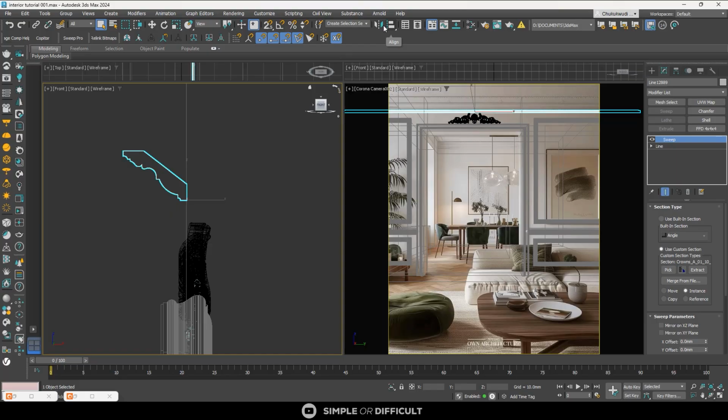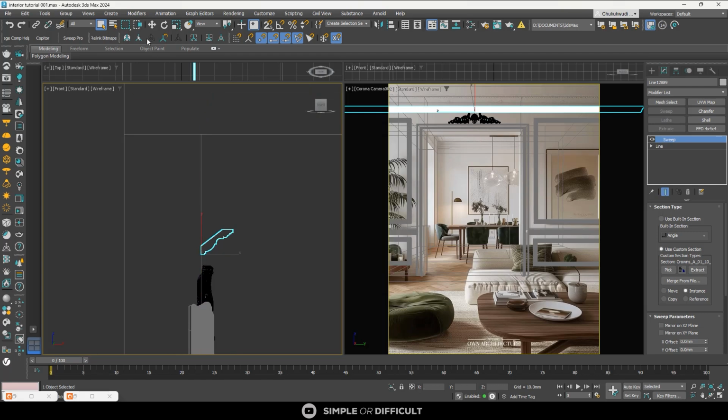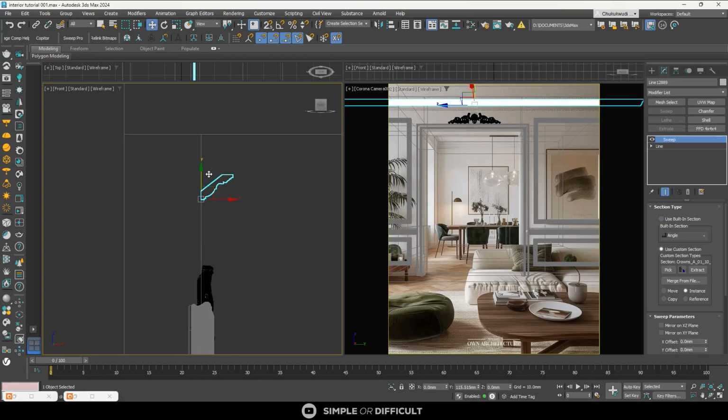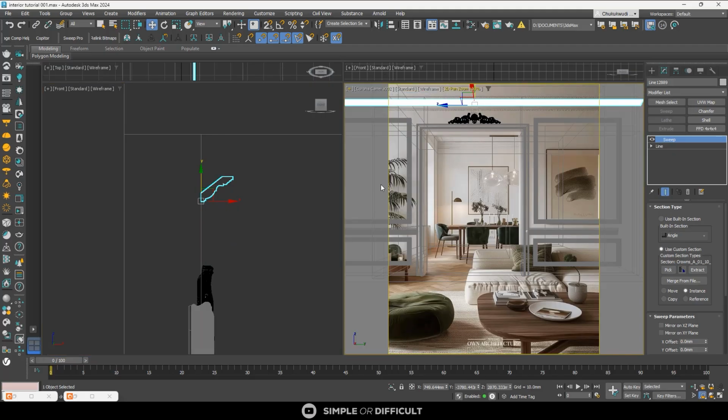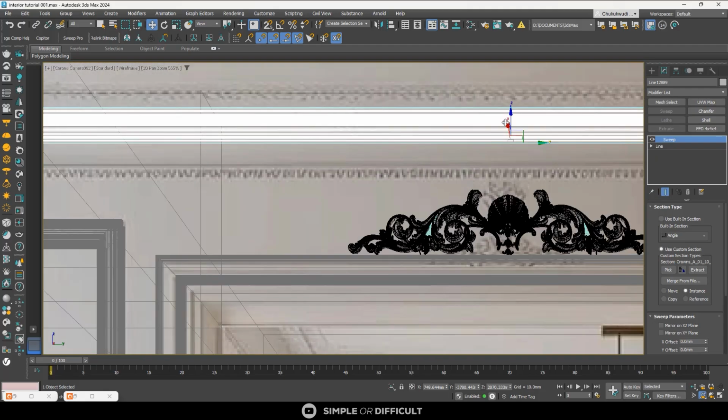But that's not a big deal. I can mirror it into position, as you have seen. So I've mirrored that one into position, and now say, okay. Let me now use the image to know how well to scale it. Now I'm going to do pan zoom or W to make it big. All right.